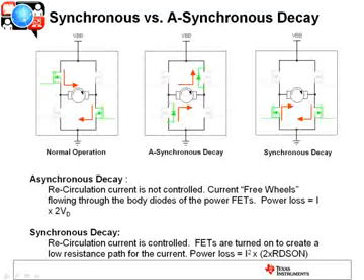So the back EMF is going to generate current that's going to flow through the body diodes there, completely uncontrolled. Now, one of the things to note there is in terms of power loss, your power loss is going to equate to the current flowing through the bridge times 2 diode voltage drops.